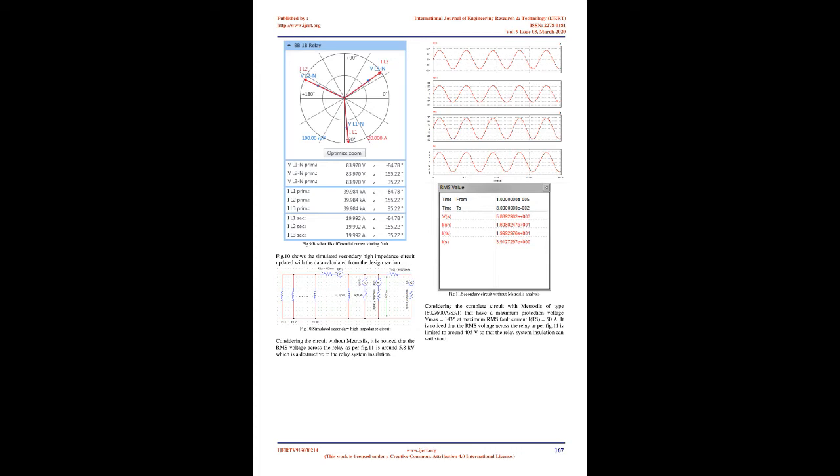F. Design of CT supervision relay. In case of minor disturbances for high impedance secondary circuits, such as wiring or loose connection, can introduce an amount of voltage across the protective relay but still will be less than the minimum operating value, VS. A CT supervision relay is required to protect the circuit by shorting the CTs as well as giving an alarm to the operators to investigate the problem reasons.